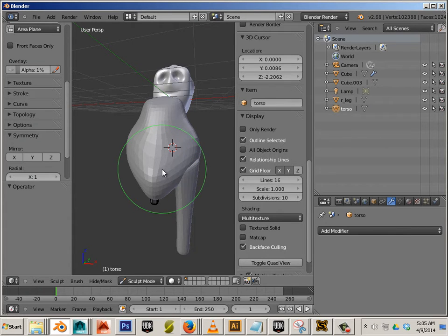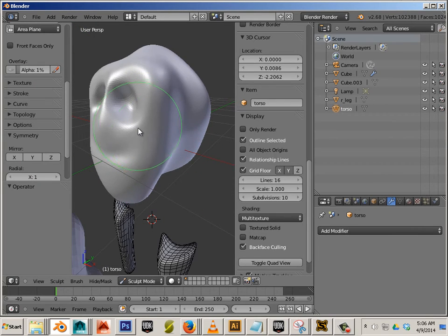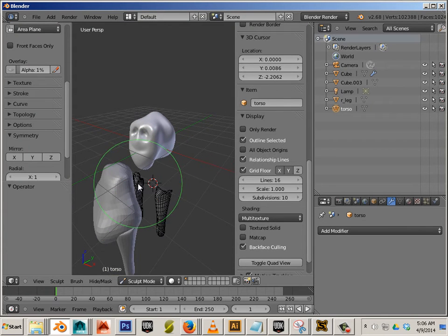That's another thing. If this one was as high resolution as this is concerned, and I joined it with another piece of equal resolution, you could essentially crash out your machine by having two pieces of geometry with 4 million polys joining. That's not good.